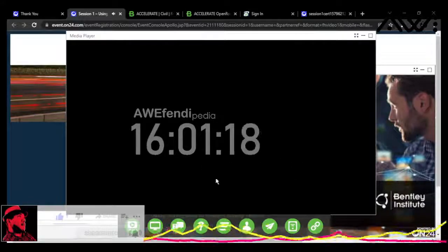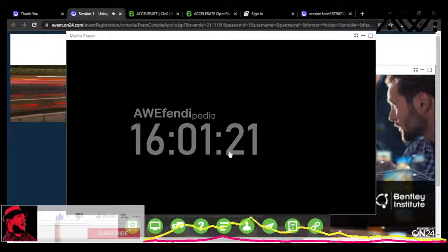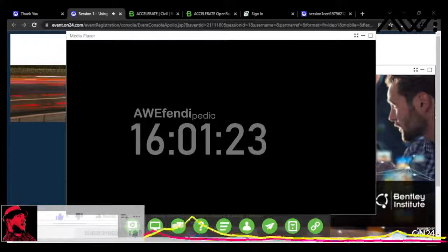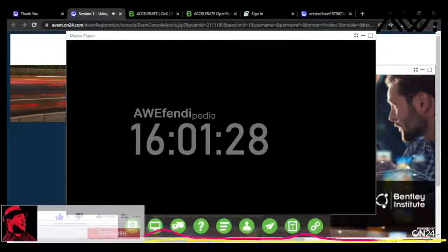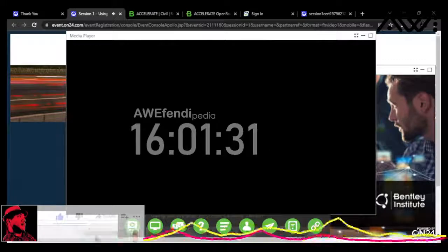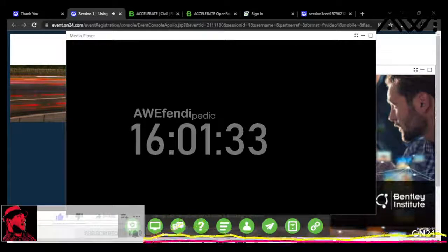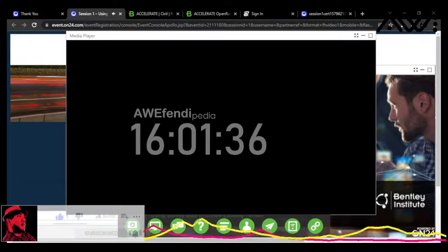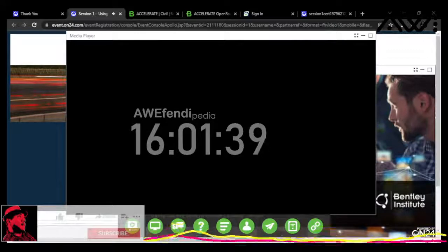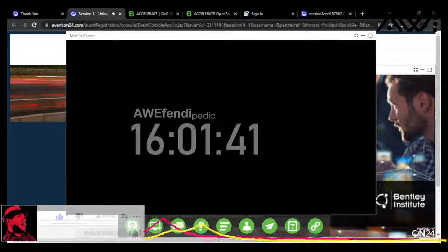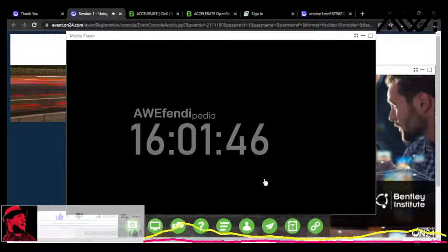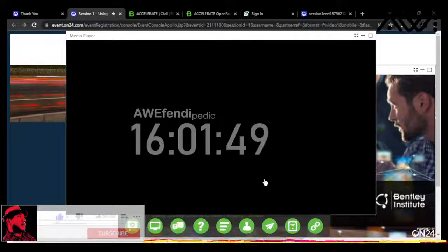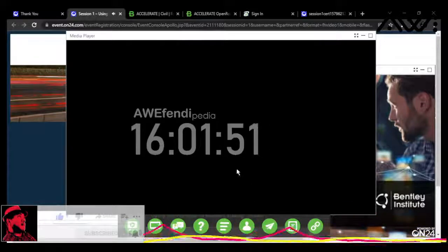Also, this data set, this is probably true with a lot of folks coming up from InRoads, it uses spaces between the feature code and the link code. So I have spaces required set to true. That's going to help me out with this data set. I'm going to link all my chains together by using the field codes and those feature codes and link codes. And then when it comes in, I'm going to keep it as a linking code feature. When the string is actually stored in our design file, it's going to stay a linking code feature. So I can still edit it with start codes and control codes, PCs and PTs and that kind of stuff.